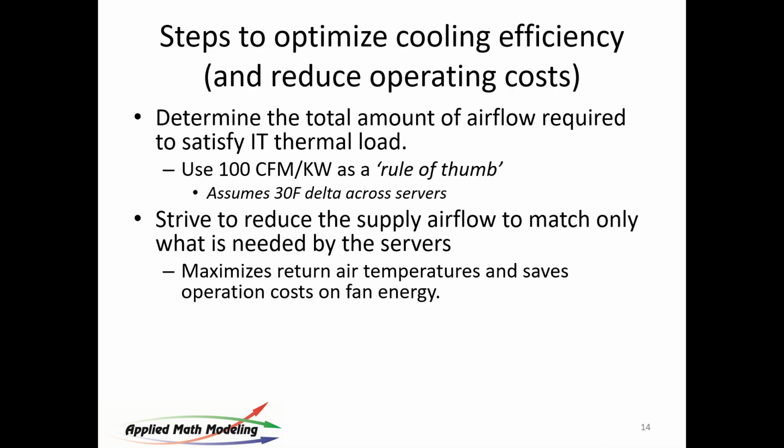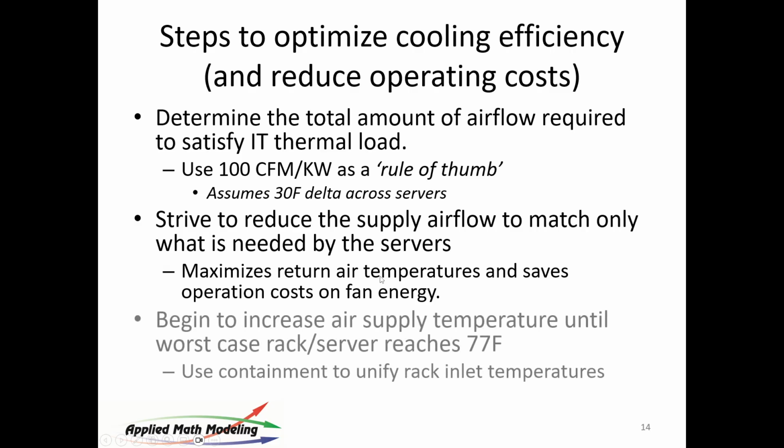That has two key benefits. One is it reduces the fan power required. Remember, that's cubic, so that's important. And number two, it maximizes that return air temperature, which makes the heat rejection system just work that much better.